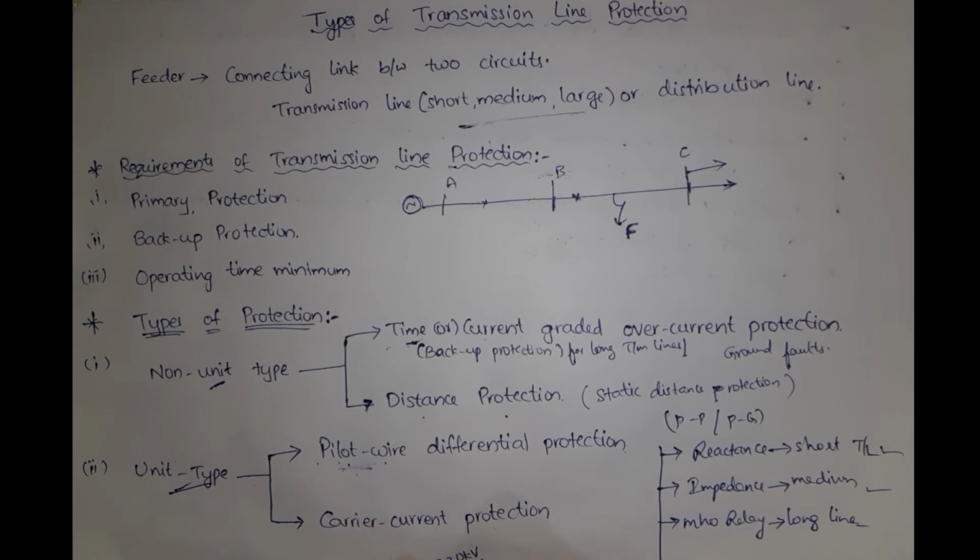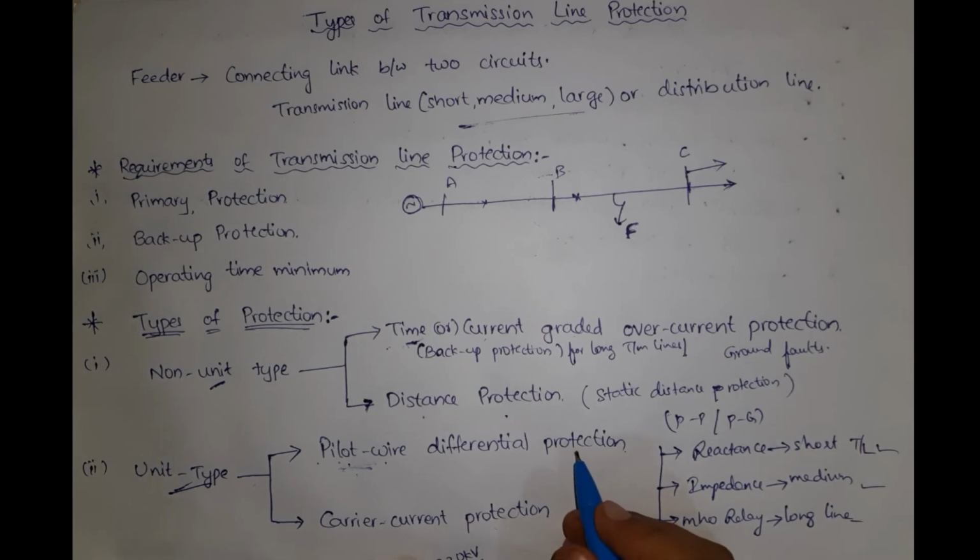Lines of 220 kV and above are equipped with carrier pilot or high speed distance relays. Okay, and 33 kV lines are provided with directional time lag overcurrent relays or high speed distance relays. In the same way, 11 kV radial feeders are usually provided with time lag overcurrent relays supplemented by instantaneous relays. Sometimes only HRC fuses are used due to economic considerations in 11 kV lines, or overcurrent relays may also be used.